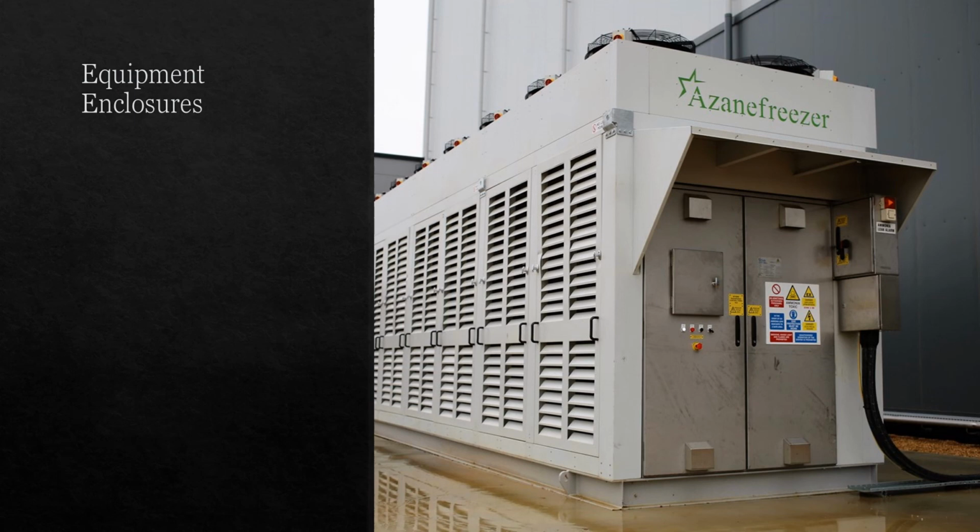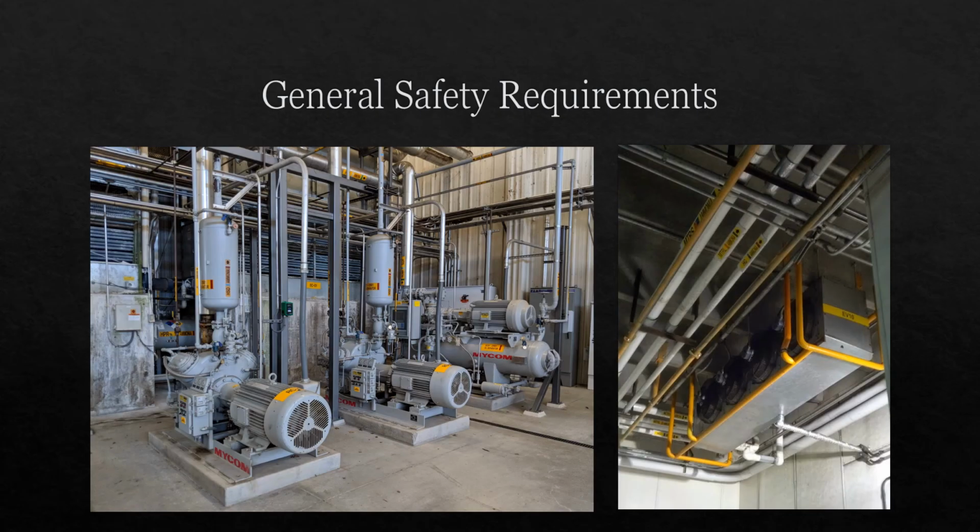Where used, equipment enclosures must be provided with protection from physical damage and equipped with panels or doors as needed to operate and maintain the equipment. Section 7.2 concludes by addressing some general safety requirements that are applicable to all equipment, regardless of age. For example, any equipment subject to physical damage must be guarded or barricaded, and equipment with moving parts must be protected by screens or guards in accordance with OSHA rotating machinery regulations.